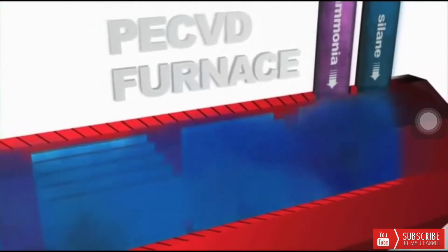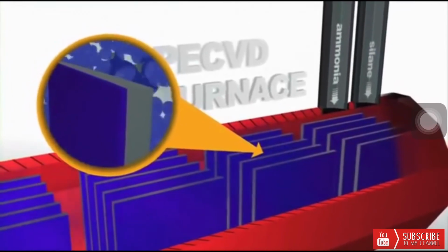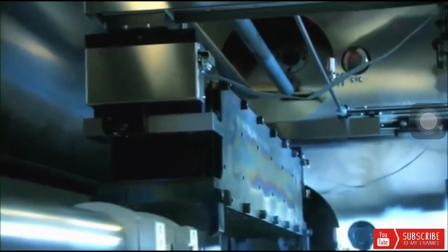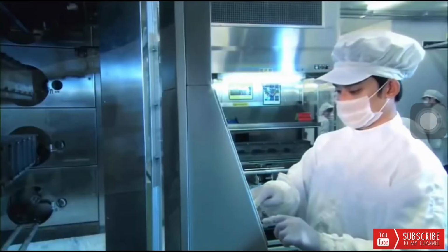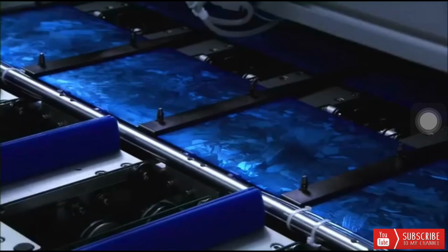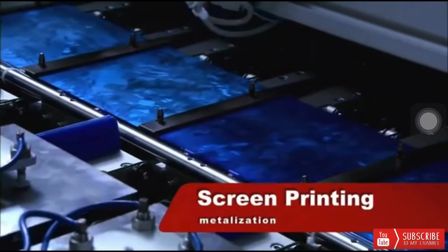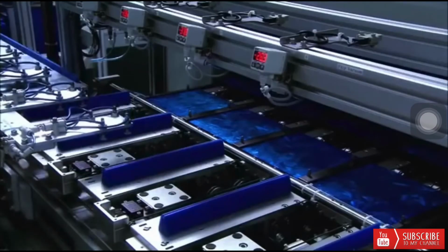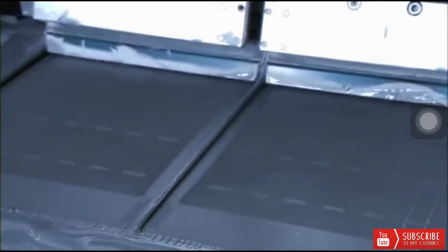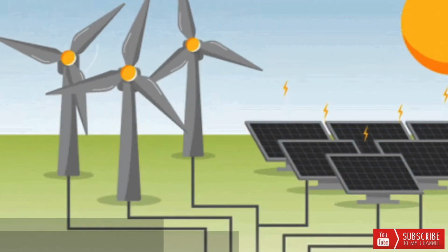To reduce the amount of sunlight lost, an anti-reflective blue color coating is put on the silicon wafer. The blue color is given on purpose to ensure the conversion of solar energy to electricity. The coating will facilitate the absorption of sunlight rather than reflecting it. Each wafer is being treated and metal conductors are added on each surface. These conductors give the wafer a grid-like matrix on the surface. This is how monocrystalline or polycrystalline solar cells are made.